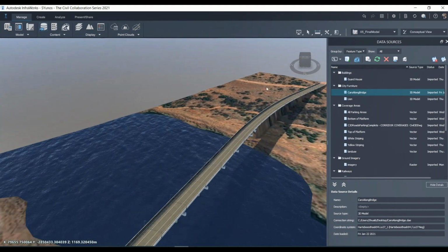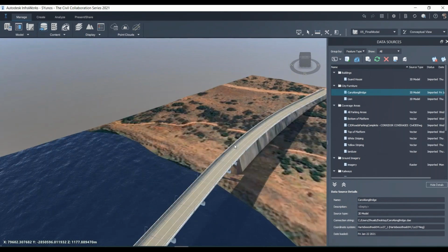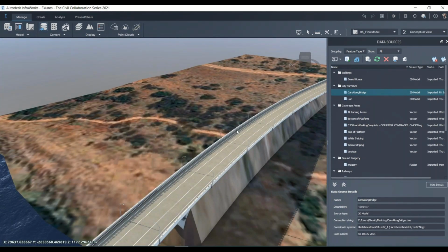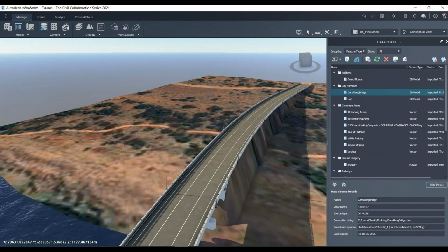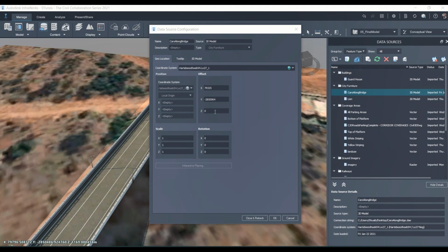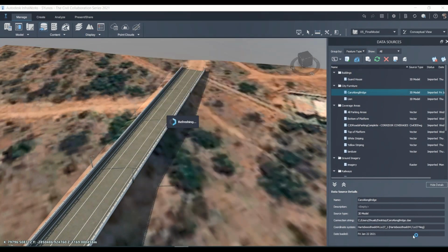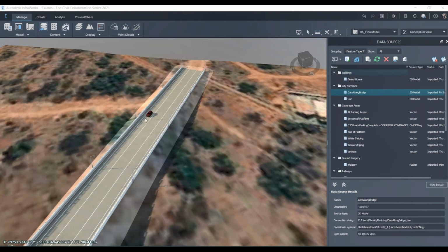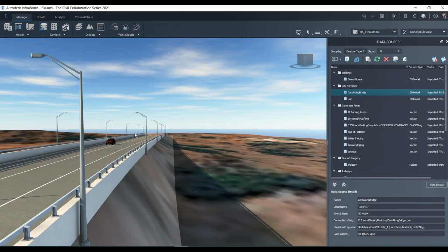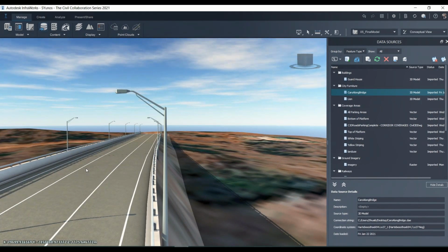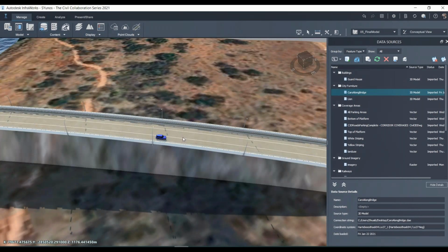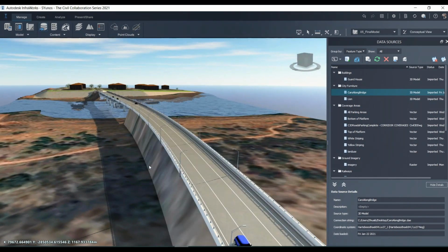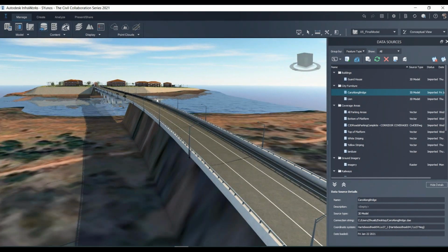So what mistake did we do here? We didn't insert a negative into the actual Y value, right? I've done that intentionally because if you import it and you don't see anything happening on your road, you need to go and check that. So let's bring that up, pop in a negative in the Y value like we've done right there, close and refresh, and here they are. Pretty cool, right? There's our Italian job going here, and we've got our Coopers running along our stretch of road. You can see there's the oncoming traffic or movement, and we've got multiple cars in each direction.